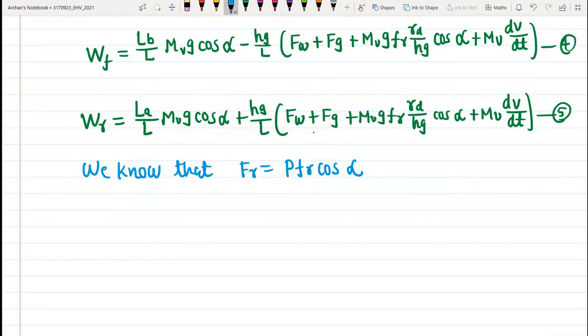So when a vehicle is operated on a slope road, the normal load capital P should be replaced by the component which is perpendicular to the road surface, and that is why this equation was there. Fr is equal to Pfr cos alpha, where alpha is the road angle.